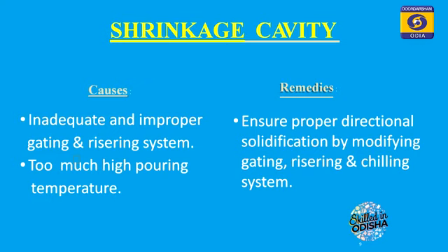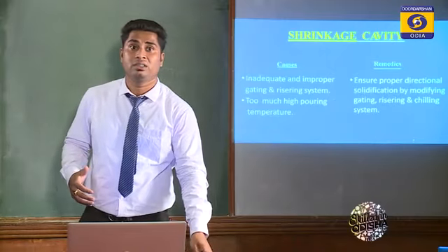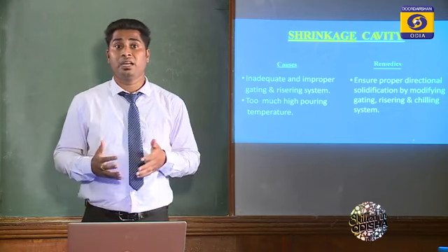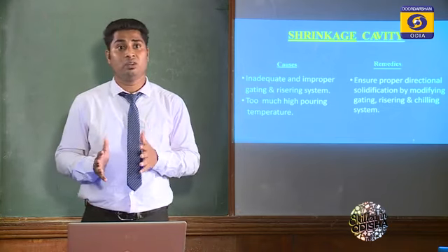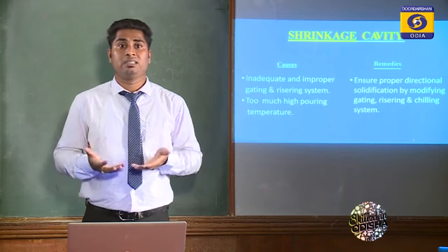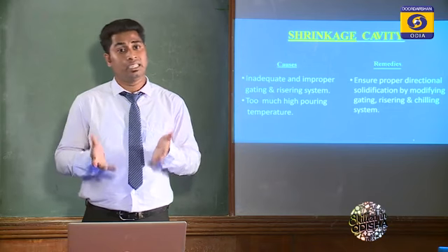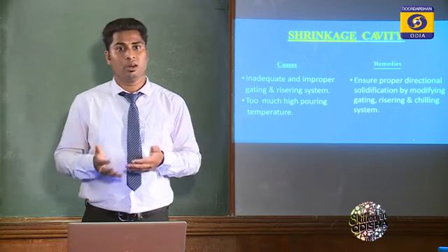Then what is the remedy? Ensure proper directional solidification by modifying the gating, risering and chilling system. I have already discussed directional solidification, which is very important in the casting process. If we can achieve very good directional solidification, then we can avoid the shrinkage defect. Okay, understood?